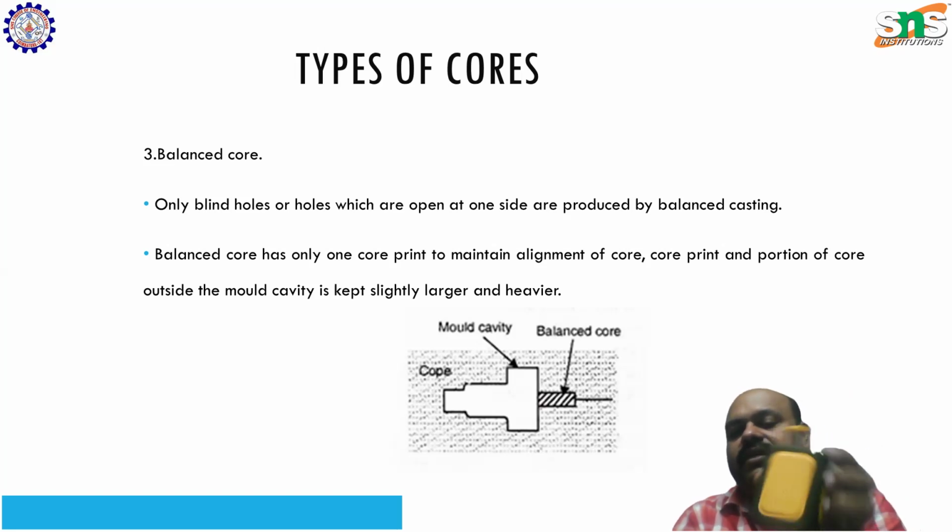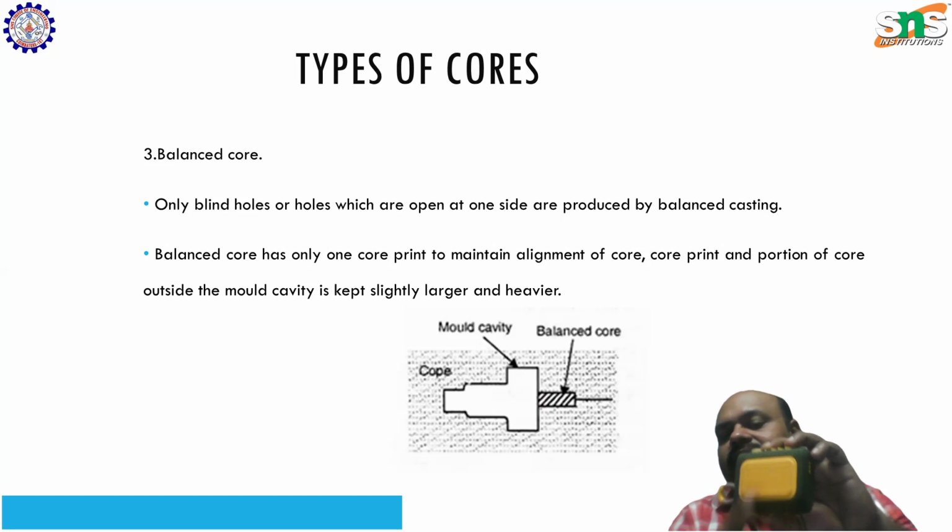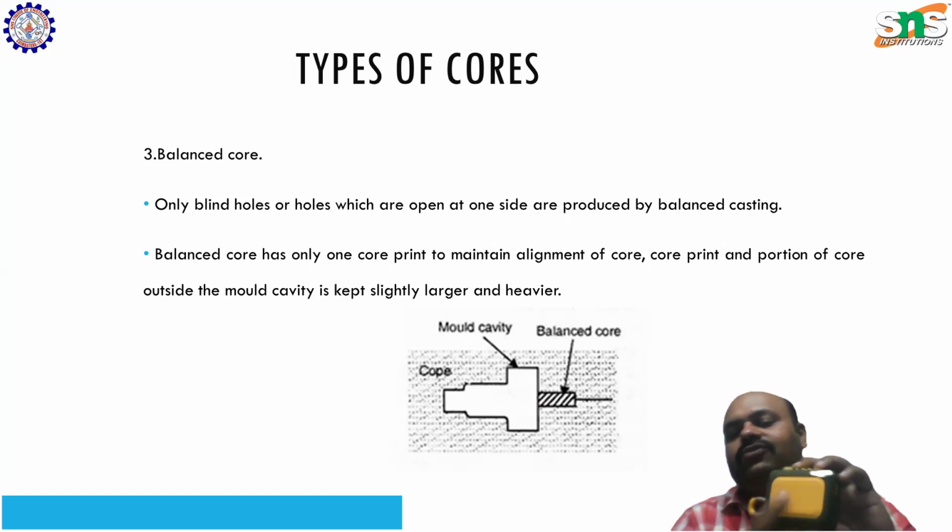What I'm showing is, imagine this as a casting. This yellow color part has to be screwed with this box, right? And that part should not have a projection of any screws, it has to be in the same plane. So we are going for Allen screws, that is flush with the surface of the part to be assembled, right? In that case, we need a hole that has to be made on this particular box, right? So we are going to have 2 points, 1 and 2. For example, one here and one other than here.